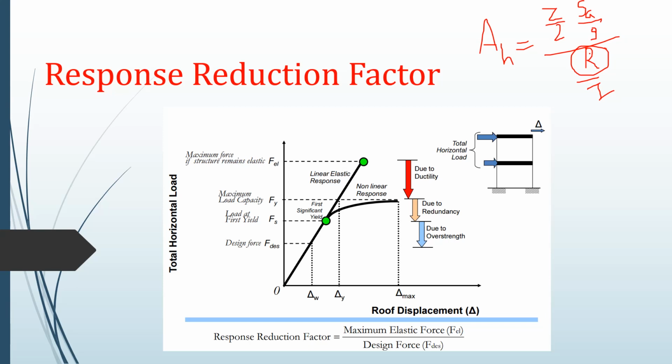So what happens is that when we construct a linear model of our structure, certain factors such as the inelastic energy dissipation in our building, the damping energy, or different types of ductility demand and capacity are not considered when we model a linear structure in our software.